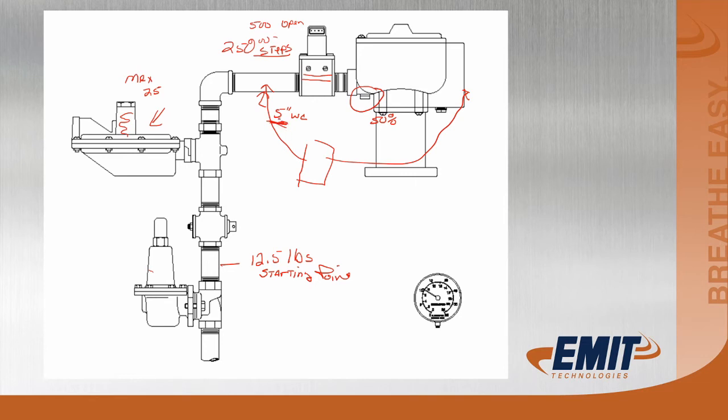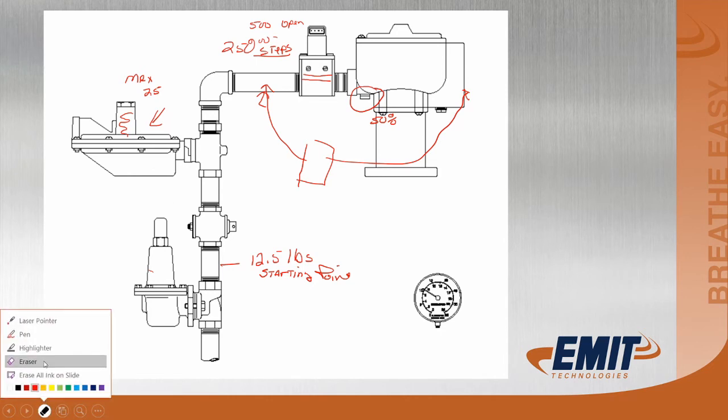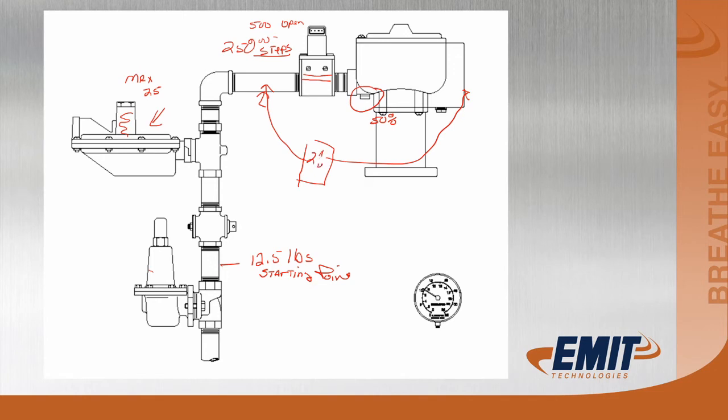One of the things you want to do, if you start putting a load on the engine and the fuel pressure would drop, you started loading the engine and now our fuel pressure dropped to say 2 inches of water column. That means we're not supplying enough fuel through this regulator, this orifice in this regulator. Now, we've already set this regulator to 5 inches. Don't go back and adjust that again. This is where most guys make their mistake. They go back and adjust that after the engine's loaded.